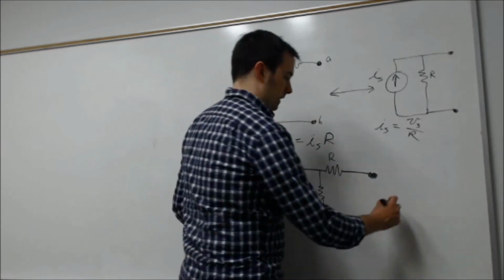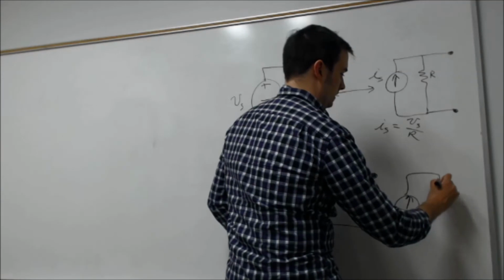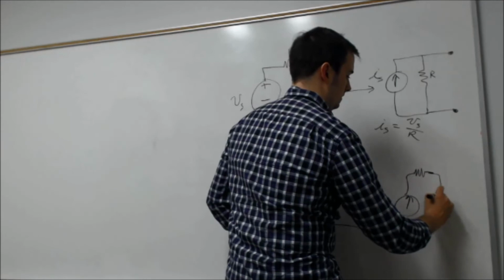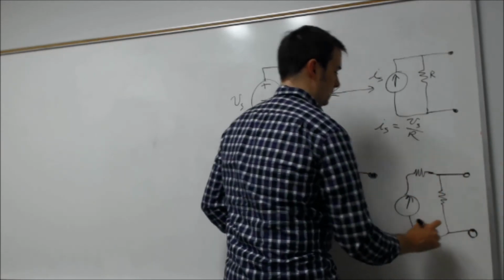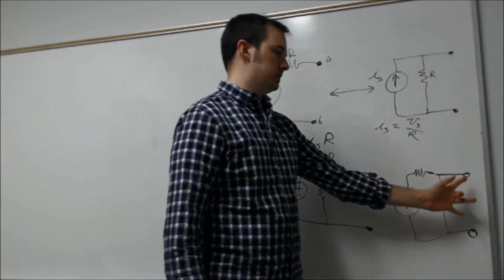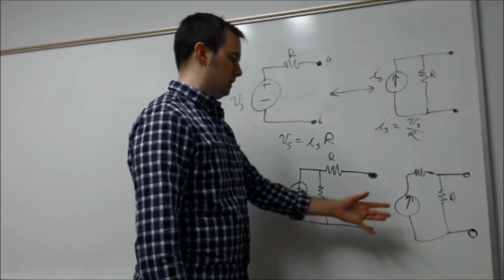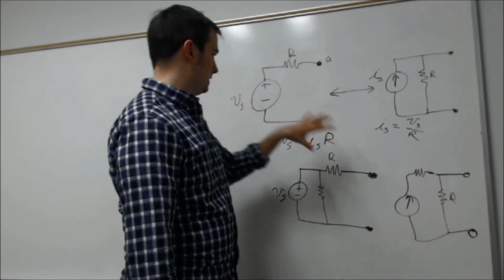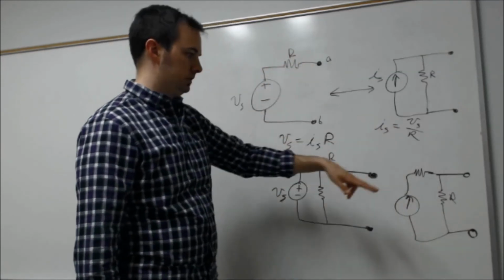And similarly, if I had a current source that had that parallel resistor in it, but also had a resistor in series, I could still do the same transformation, despite the fact that I have this extra resistor sitting in there. There ends up being no net impact at my terminals, which is really what I need to be sure I'm equating to. So if I had this situation, even with that extra resistor here, I could still transform this into this configuration using the same method. Don't need to add anything extra with this resistor value.